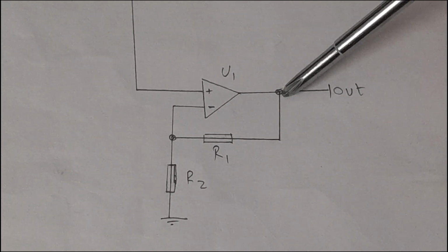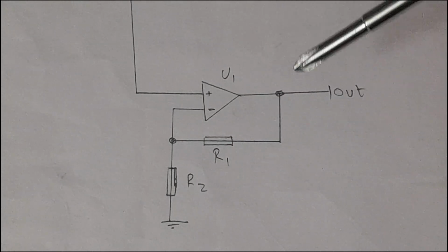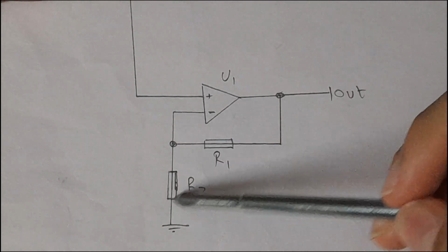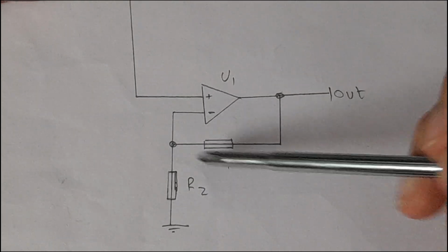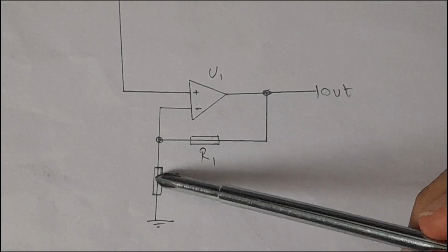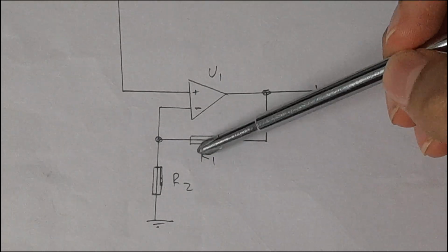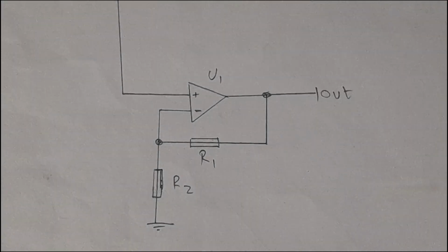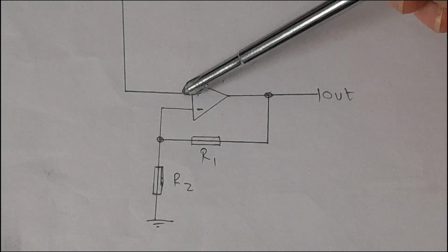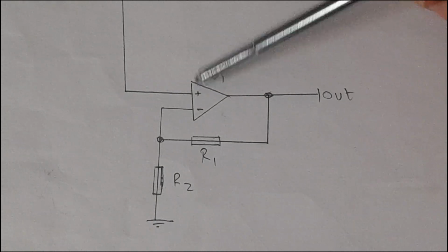This is the voltage amplification circuit, and it is very simple. Basically, we are connecting a resistor divider at its feedback. If we connect both resistors with the same value, then we will have a gain of 2. So now let's provide the op-amp with 12 volts. The 12 volts is coming to its non-inverting input.